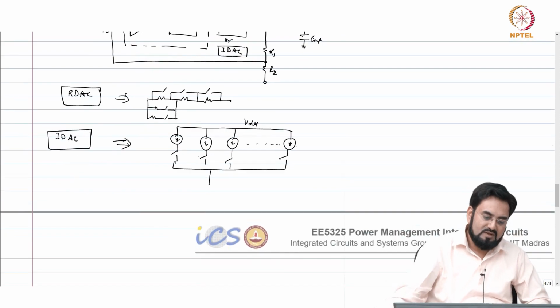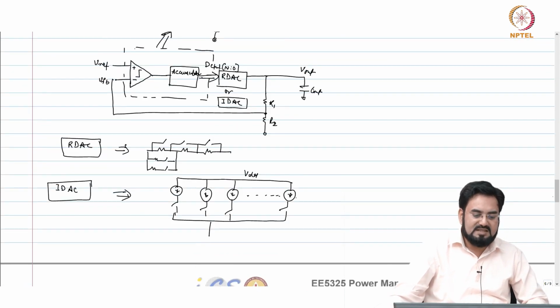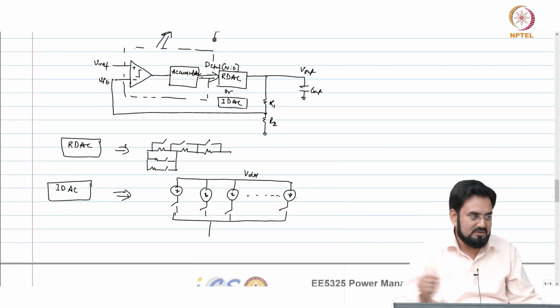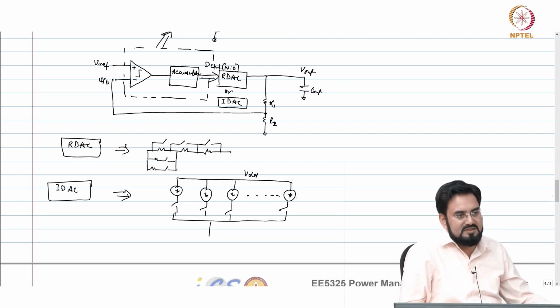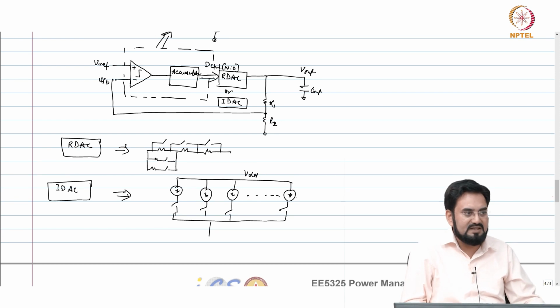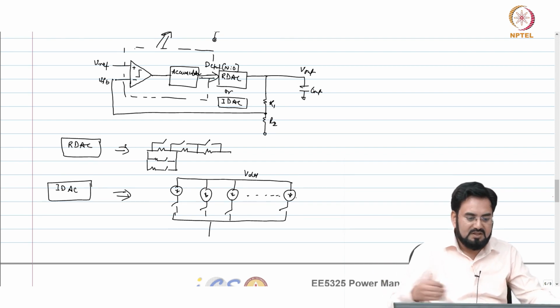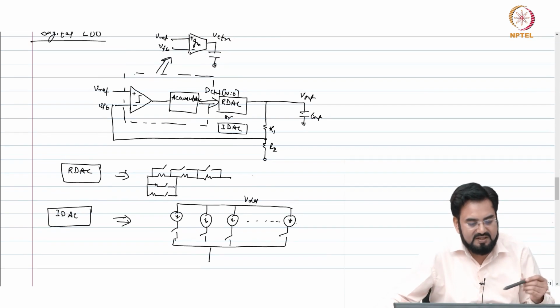And these resistors can be replaced with simple MOS on-off switches, and the RDS on of those switches will define the resistance. When you turn on those switches fully, that will be linear, in the triode region, and whatever the resistance is will define the unit resistance. You connect them in parallel and series, and you get the value depending upon your need. So this loop will automatically take care of that.